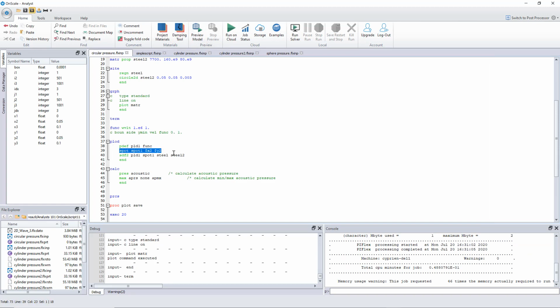Except that this time I'm using the spot. And you see that I set up the key points. Sorry, this is not key points, this is a position. So position is x2 and y2, which refers to the middle of the plate. This point will fall right in the middle of my center circle. Because of that, the spot will select this circle, and this will at the same time orient the pressure towards the borders. You can think of the spot as some kind of light going down to a specific point, and then setting up some kind of normal axis to this.